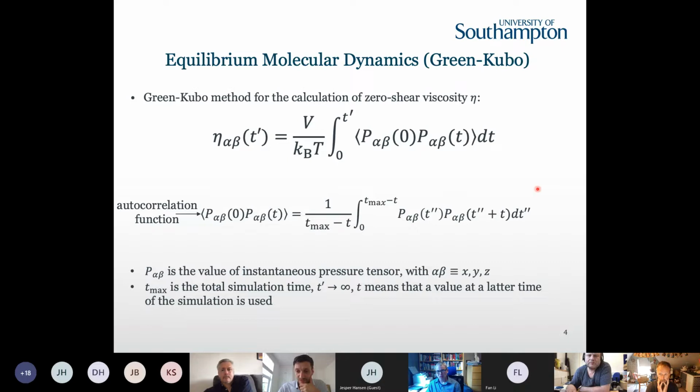Yeah, I must admit, I'm not a big fan of LAMMPS or any of these packages, because I once tried it for Couette flow of a WCA fluid and got different results to what is in Denis Evans's book, and different results, and results which I agreed with an independent calculation. So there's something funny about LAMMPS and how it deals with Couette flow, and I think it's due to the thermostat, but no one's really got to the bottom of that. So I personally don't trust LAMMPS for anything NEMD.